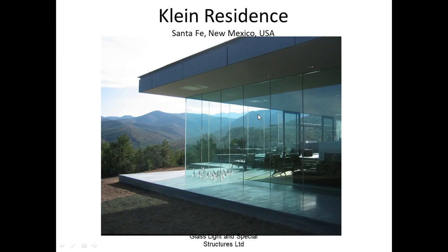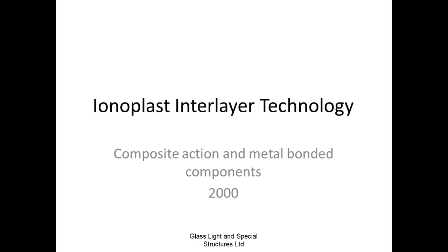It's not some clever cantilever. There's nothing going on inside. The roof is being carried by the glass. So this is where we are now in terms of structural glass technology. It's a load-bearing wall, which traditionally would have been reinforced concrete, stone, brick, what have you, generally lowish tensile materials. And here we are with the structural glass wall, which is really wonderful.